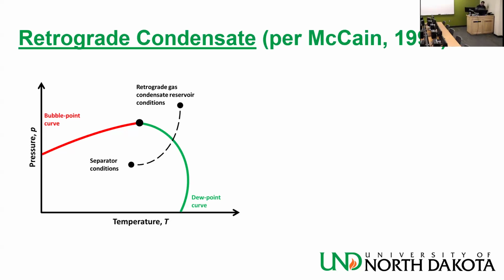This is how it works. We start from gas, we cross the dew point line, we get the first droplet of liquid oil coming out here, then more, and then less. So you need to keep it at the region where it produces the most. We are really going to try to achieve that with liquid blocking. It's almost like doing a water flood, but from all around the directions. And then you want to keep the pressure at a certain range, and sometimes that range is very small. It's very difficult to nail it, you know?